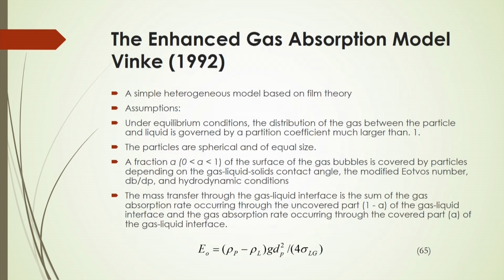And there are various other solutions given by different investigators. In this case, the enhanced gas absorption model was given by Vinke, 1992. I think it will be helpful to follow this literature to get the enhanced gas absorption model for mass transfer enhancement in the gas liquid solid fluidized bed based on the film theory.